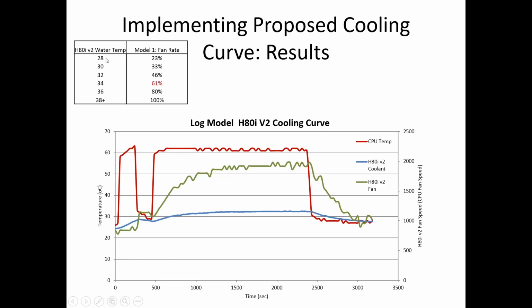So, using that relationship here of fan rates, we've programmed that curve in, and you can see this is the response. We see as the processor produces heat, and throughout that whole process, because that cooling curve is matched to the system, we see that there's no overshoot or undershoot on temperature. It's very well tuned, and the CPU temperature just reaches a steady threshold throughout that whole process.